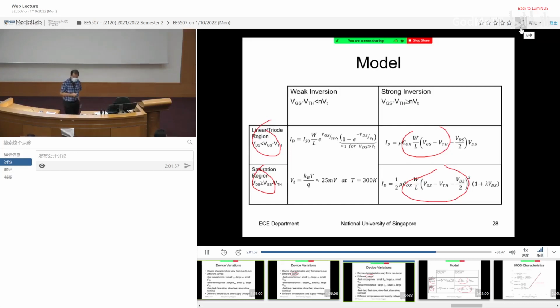How can they do that? They operate the device in the weak inversion region. Even for wake-up receivers, people are reaching sub-nanowatt, reaching 400 picowatt. Okay? Of course, whether they can reliably reproduce this is another story. But these are the state-of-the-art performances. So these are the power consumptions people are looking at. So why do people go to this extreme? Nanowatt, picowatt. Because they don't want a battery. They want to use just a photocell. Okay? Just light shining on it will provide sufficient power to power the circuit. So the circuit can run forever. They don't need a battery. So that's why they target very, very low power.